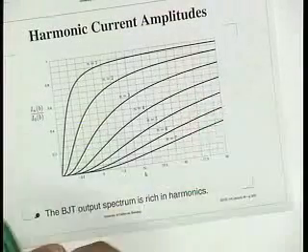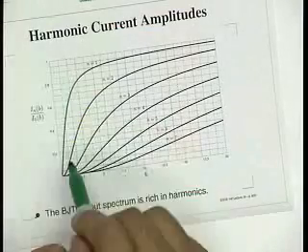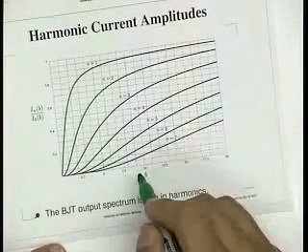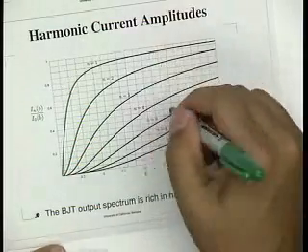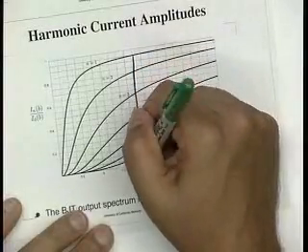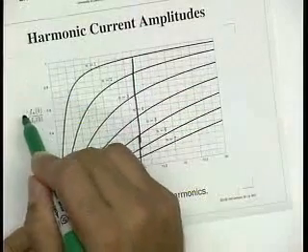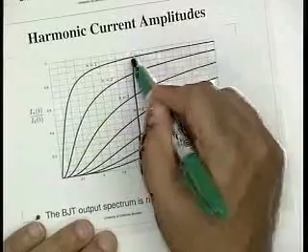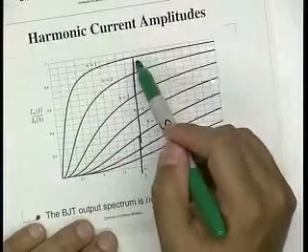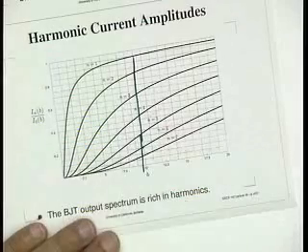And so basically for any given value, the x-axis here is B as a function of the input drive, and the y-axis is the magnitude of the nth harmonic. So if I have this table, I can just look up for any value of input drive what the various harmonics are going to be. So for a value of B equal to 10, you can see that the first harmonic is actually approaching 2, because remember the actual harmonic is 2 times this. For a very, very strong overdrive, the first harmonic is actually twice as big as the bias current. And then the second harmonic and third harmonic and so on and so forth.